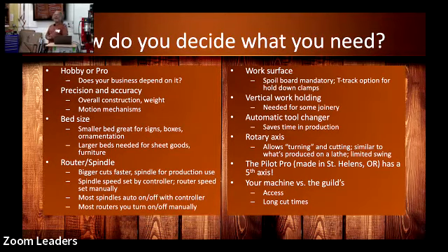How do you decide what you need? Well, there's a lot of different factors. You're a pro, you're going to use this in professional work. You're going to want something pretty reliable because when the deadline comes and the router motor burnt out because you used it too much, that's going to be a problem. So maybe a spindle will give you more of the reliability that you're looking for. The precision and accuracy is going to be more important for the kind of fine work that Tracy does when she's carving for the joinery work and so forth. But if you're going to be carving some letters on a sign and a plaque and stuff like that, you don't need to get it down to mils.